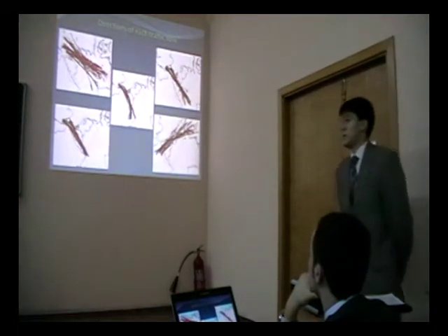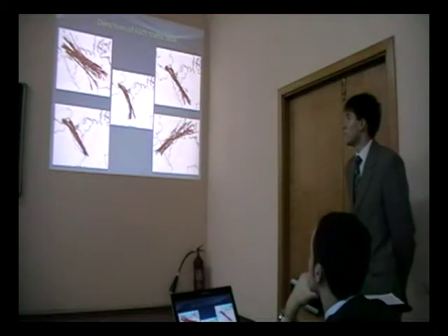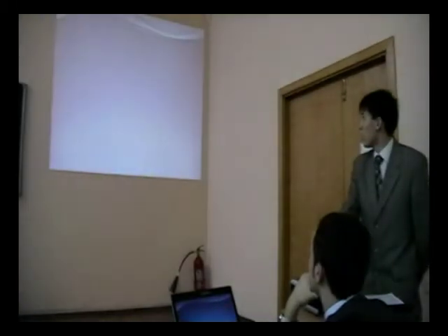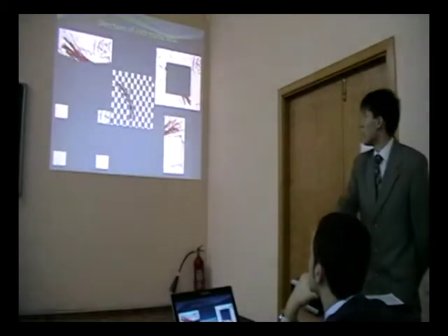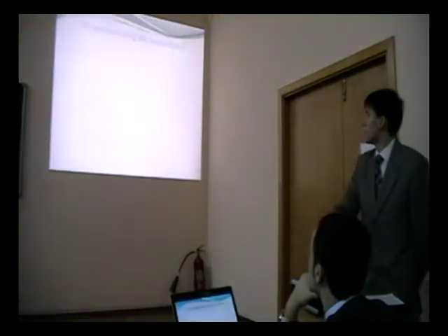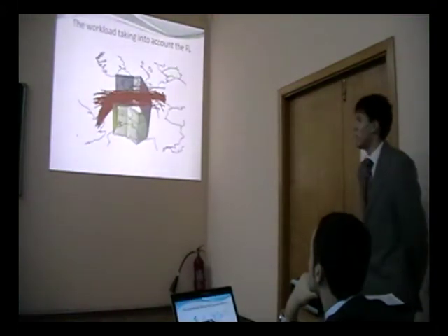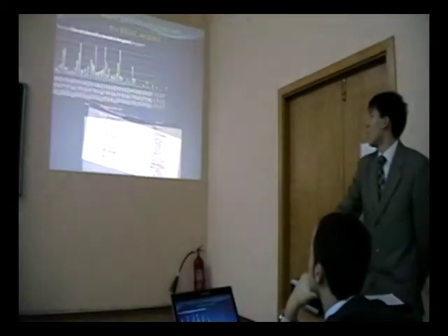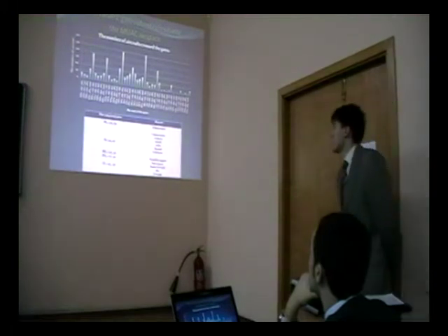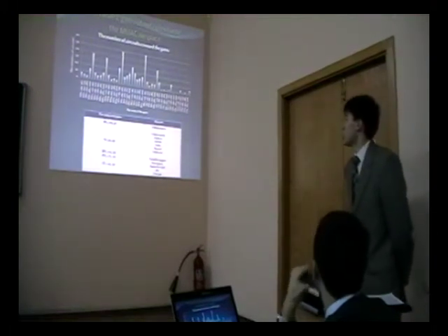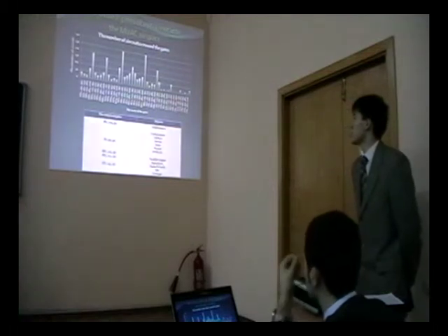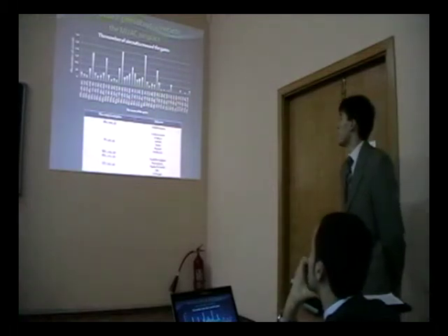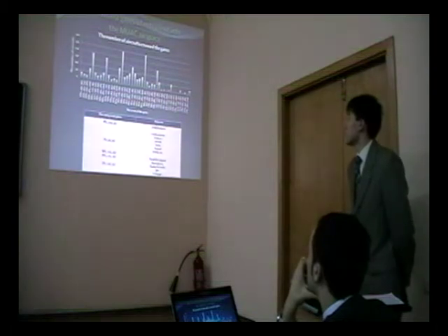With this tool you can create your traffic scenarios, investigate and estimate the main directions of flows, and also the workload taking into account the flight level. During my scientific work, I have estimated the workload of MOAC airspace and found the busiest entry-exit gates in this airspace.